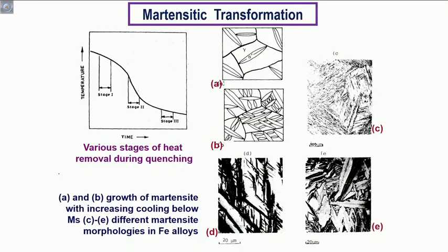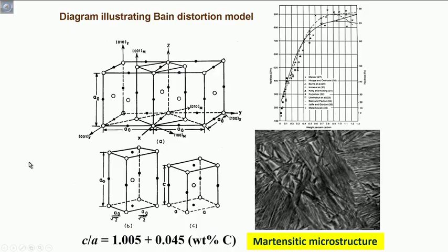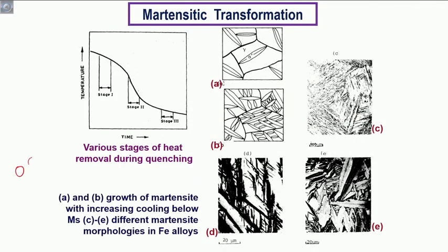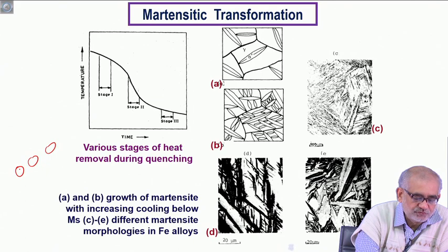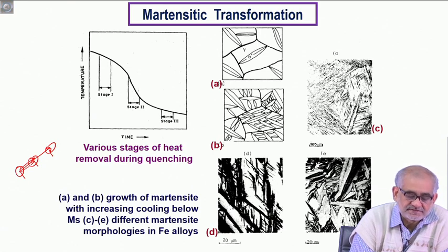So let me just clarify this part right away. When we talk of diffusion control, what we mean is that in a given lattice, if we have atoms located in certain positions like this, when the atoms move, they move from one designated position to the next, and so exactly the distance of separation from one jump, or the length at which an atom will jump from one position to another, will be exactly the multiple of interatomic distances.